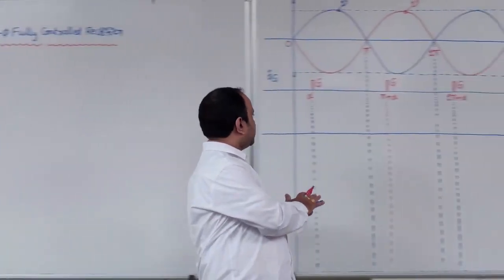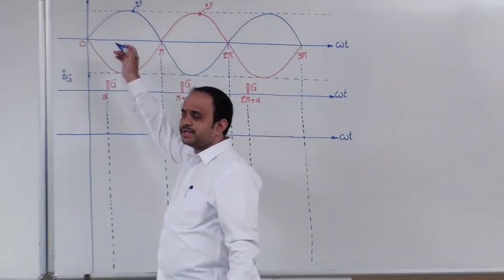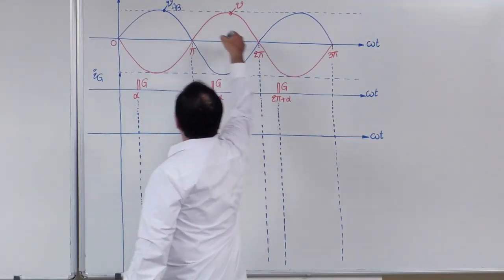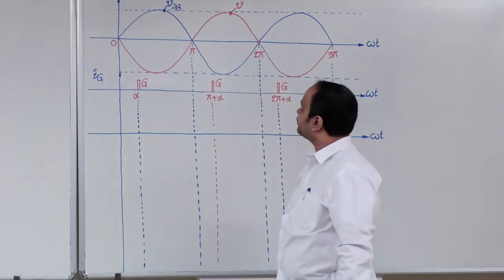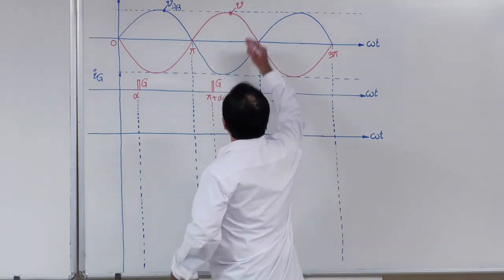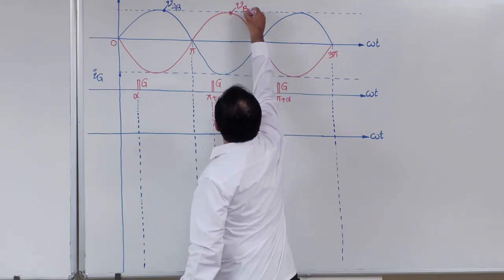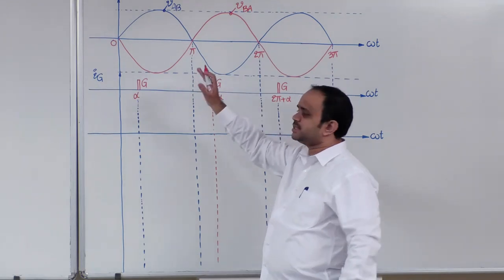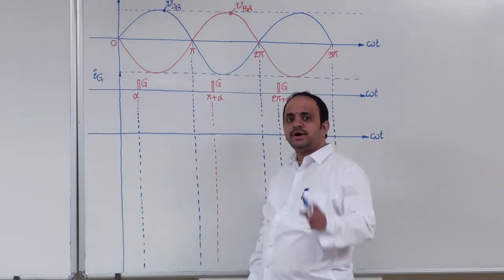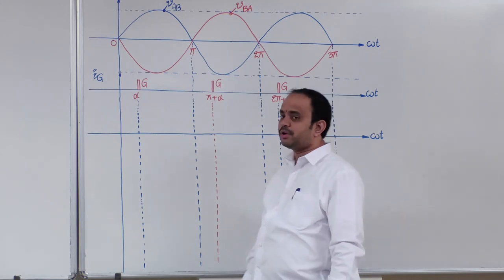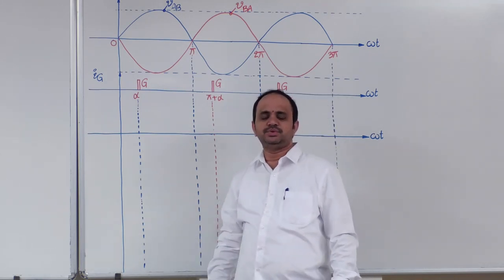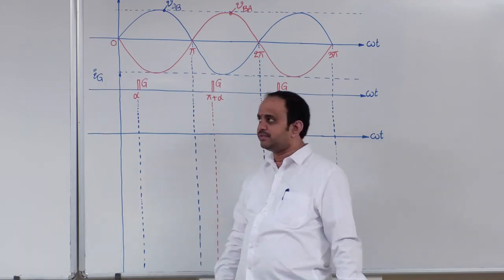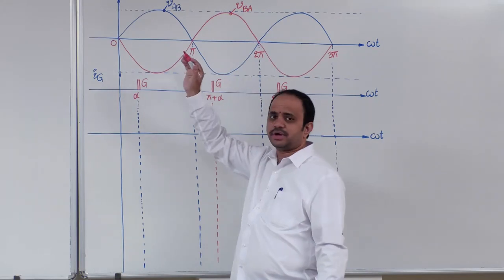Here I quickly plotted source voltage VAB, which is the blue color sinusoidal like that. And the red color sinusoidal is simply VBA. VBA is just the mirror image of VAB. Now remember carefully, in the earlier midpoint converter there was a second winding to create that VBO, but here such a scenario was not there. However, VBA is plotted.